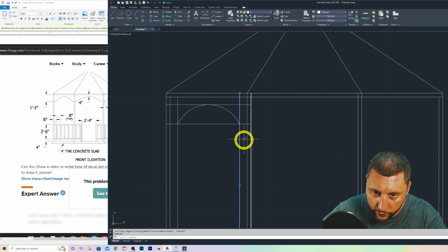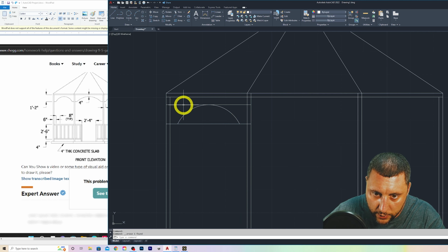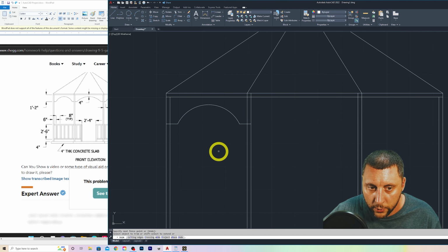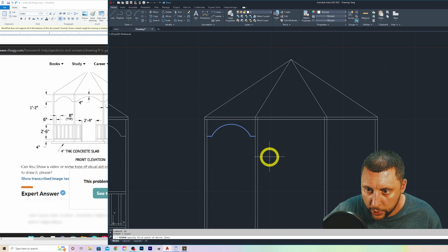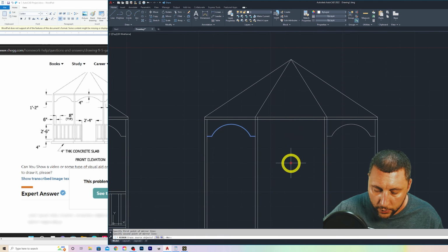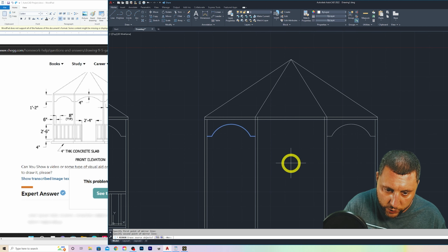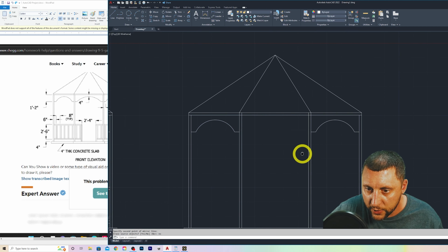After you get that, you can get rid of this line, you can get rid of this line, you can get rid of that line, and then you can trim that open. And then, oh yeah, also you don't want that and you don't want that, okay? Now, good news, this can be MI, enter, mirrored over the midpoint, straight down, and then you can do erase the source, no. All right, so now you've got the other side.